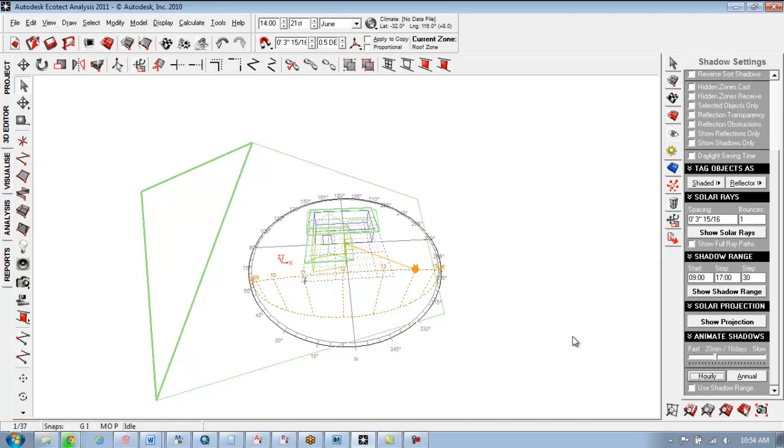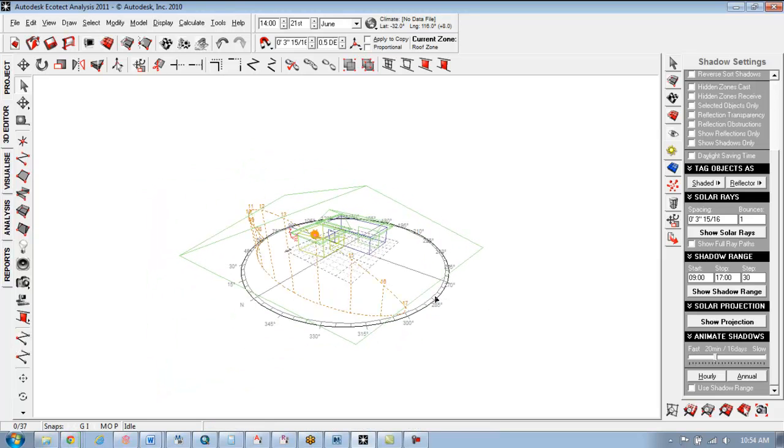Okay, so just at the very end of the day, and there's actually a way to calculate shading as well. So you can find that it was only 10% shaded for one portion of the day. But yeah. So there's no way to create like trees or other shading devices in Ecotect, so you would just have to create like planar surfaces or obstructions, or if you wanted to model the building next to it, you would just create a 100-foot zone or whatever it is next to it and then see what kind of effect that shading had on that structure.